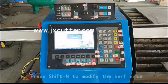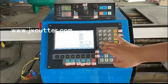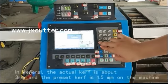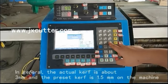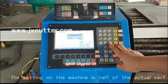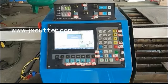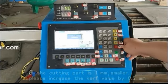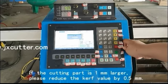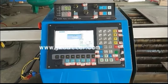Press Shift N to modify the kerf value. In general, the actual kerf is about 3 mm and the preset kerf is 1.5 mm on the machine. The setting on the machine is half of the actual kerf. If the cutting part is 1 mm smaller, please increase the kerf value by 0.5 mm. If the cutting part is 1 mm larger, please reduce the kerf value by 0.5 mm.